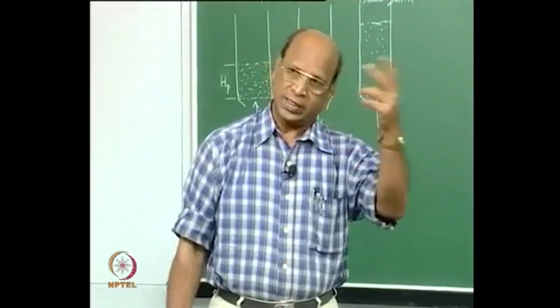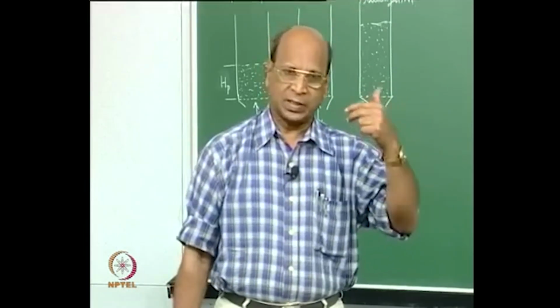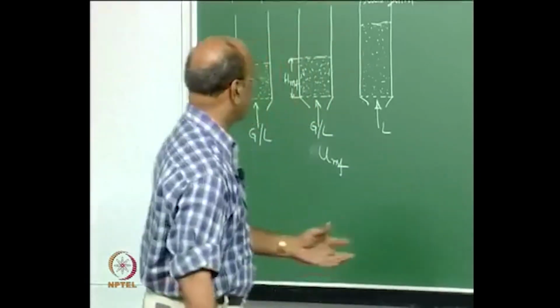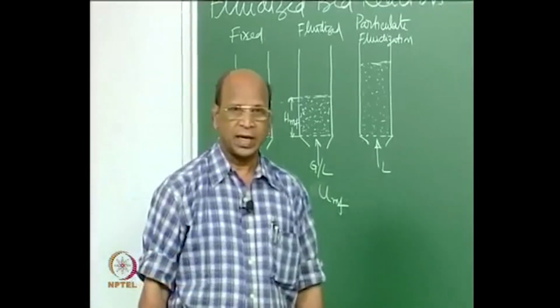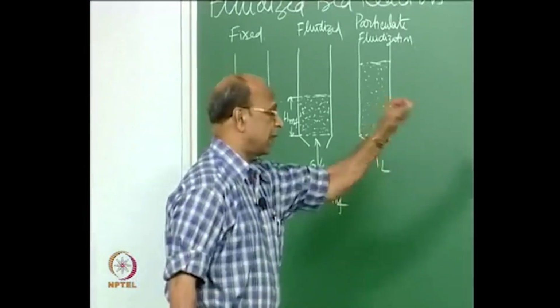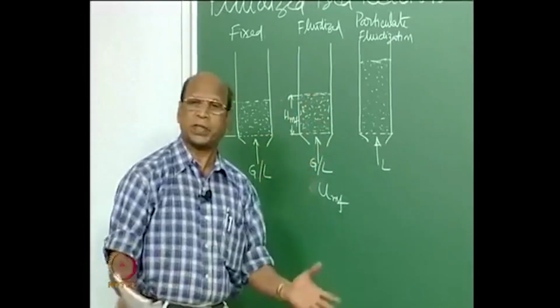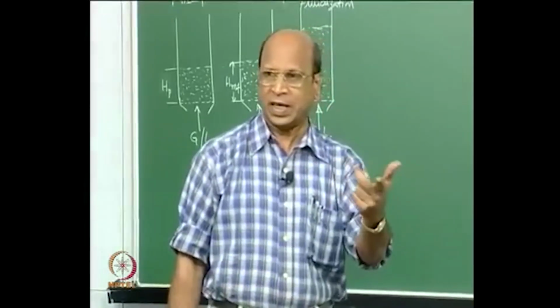So, beyond that you are increasing velocity. So, drag force will be definitely more. So, when it is more, what is happening, how it is transformed? The drag force is transformed in the form of expanding the bed. But if you take the pressure drop, I will come to the pressure drop later, at this point onwards you have the same pressure drop for the solids. Weight is not changing, I mean, weight is same.